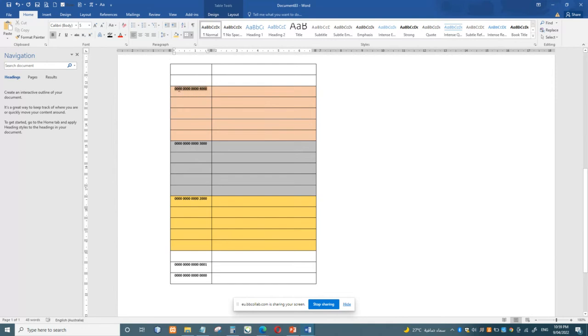By using this starting address, we can access any particular byte within the block, within the segment. Say for example, one of the registers contains this starting address of the memory location, and your instruction contains the displacement: how far from the starting address of your block is the memory location that contains your operand. So for example, if your operand is here, this contains your data.